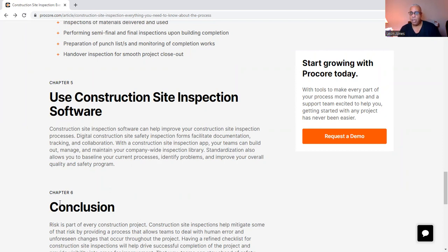And again, you as an inspector, you're out there collecting tickets. You're the one totaling up the tickets to get the quantity. You're also documenting where the material was placed. You're looking at the material to make sure that it arrives on site properly stenciled, like a structure for a box culvert, a structure for a manhole. Now I'm talking about road projects, but you're going to do the same thing when it comes to building projects.